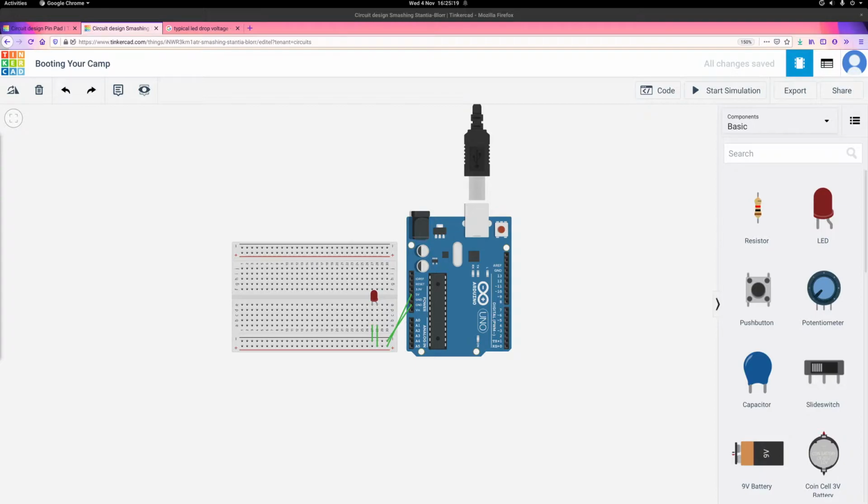Because I think essentially all you'll need is Ohm's law, and I guess if you want to be particularly exhaustive, Kirchhoff's voltage law applies here as well, which is the one that says around a loop, the sum of voltages is 0. So we'll be losing some amount across a resistor, losing some amount across the LED, and then adding 5 volts. So basically, the voltage lost here and the voltage lost here just need to add to 5.